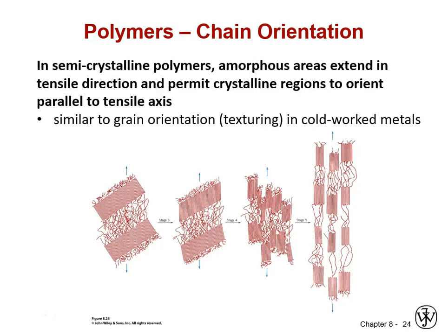So this diagram, a schematic looking at the progressive reorientation of a semicrystalline polymer, kind of gives you an idea of the difference between metals and polymer materials. This is a thermoplastic. The chains are not cross-linked. They're not a big 3D network of covalent bonds, so they're being held together by chain entanglement. This is obviously a semicrystalline polymer with little ordered lamellar areas being the crystallites.